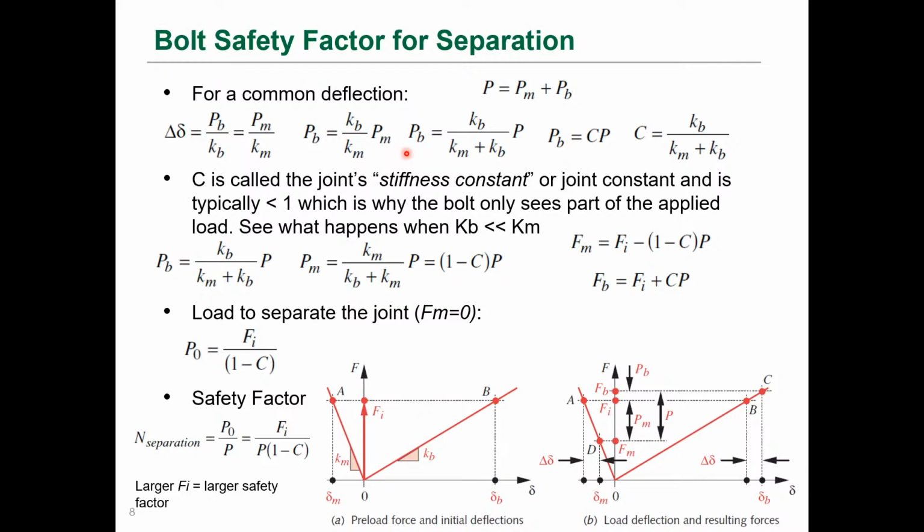What we're concerned about is making sure that when we design a system, the joints won't separate and we don't exceed the bolt stress. We already showed that the load applied to a system, a clamped joint with some material and a bolt, is picked up by the material and the bolt, and the change in deflection is going to be the same for both of them. The deflection is defined as the load over the stiffness.